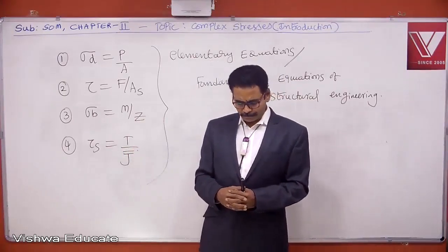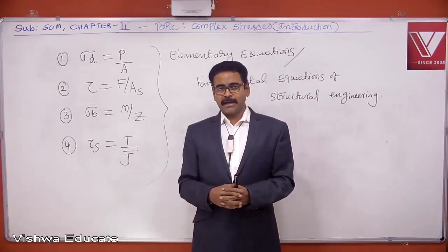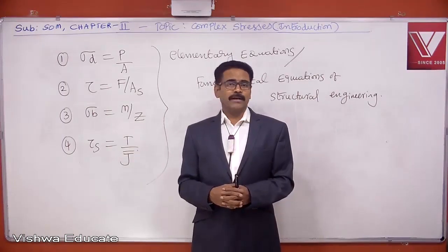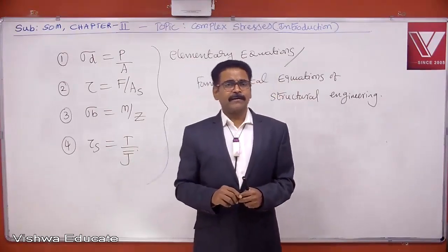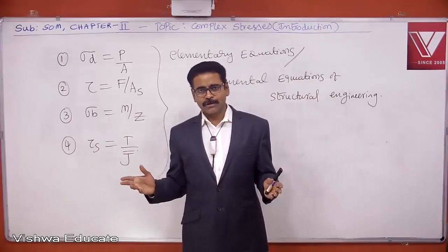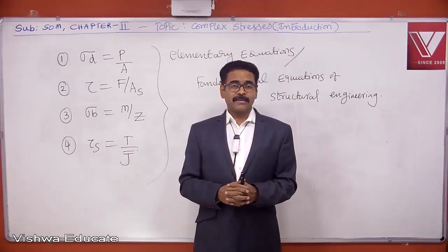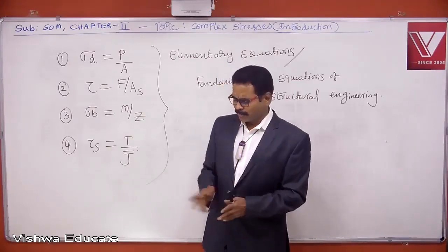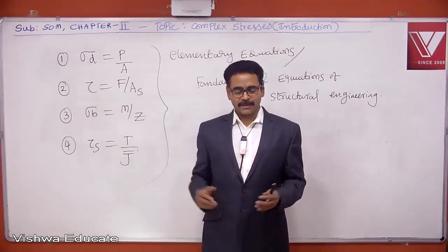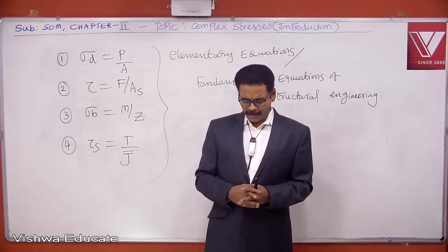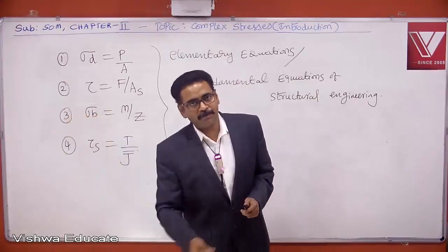Now a question may come. Why do we have to find the angle of major principal plane and the angle of shear plane? I already told you, brittle structures fail about the major principal plane and ductile structures fail about the shear plane. So first you use some formula and find the angle of the major principal plane in a structure. Then if any failure comes in that brittle structure, it should come about the major principal plane.